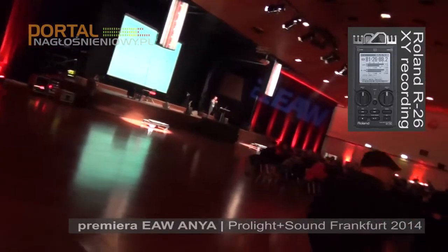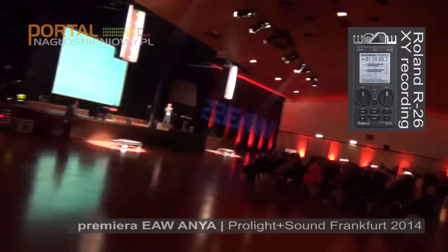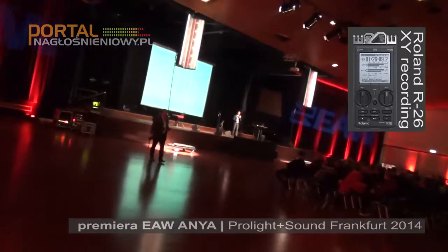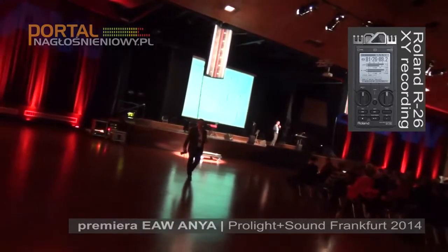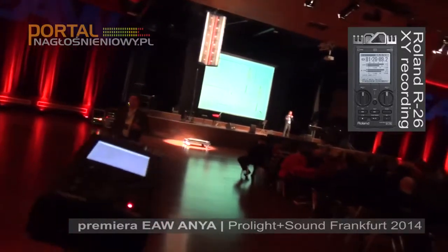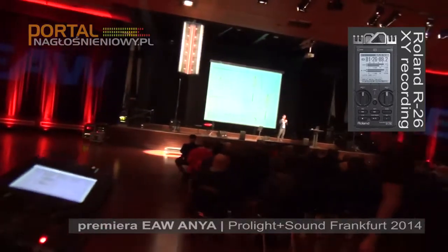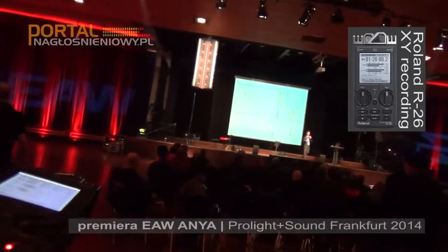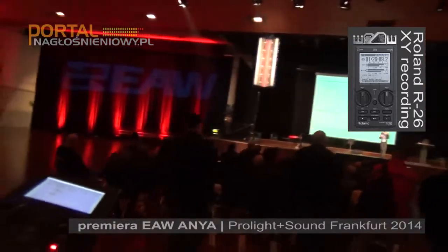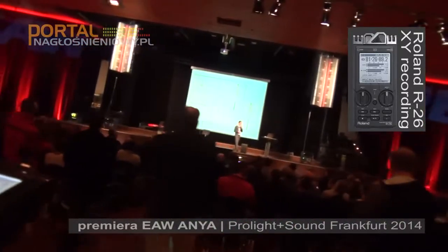Second, the high-frequency spacing was such that we didn't really have the ability to radically alter the vertical coverage, meaning that we had several dedicated modules within the KF900 line that directly addressed all possible scenarios that you might experience in a venue or a given number of venues. And last, and perhaps most importantly, there was no user-accessible software package that allowed a user to easily and quickly configure the system for night-to-night or even within a performance, any changes that might be necessary.